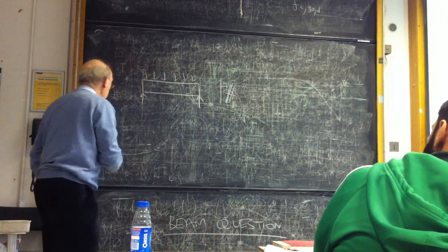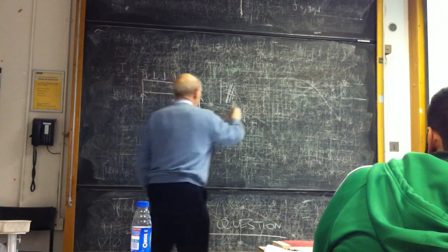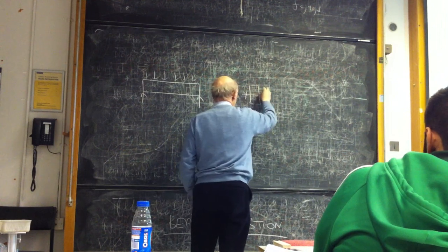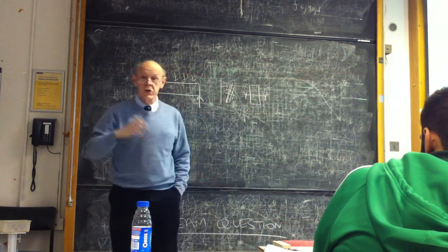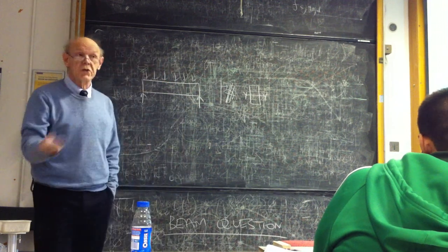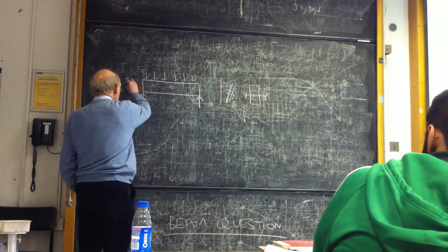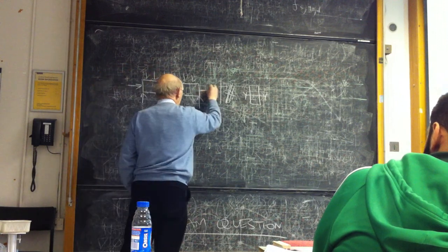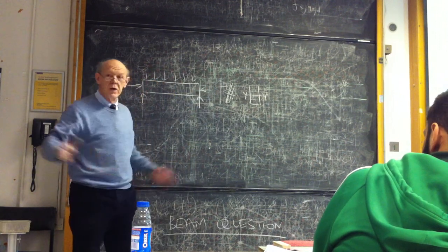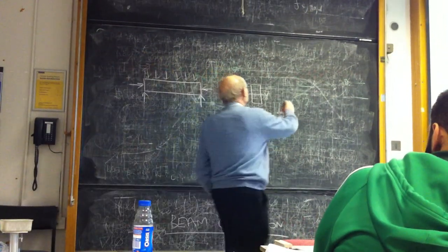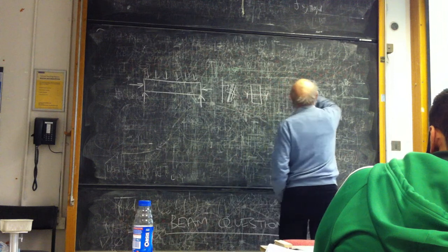Now this might get even worse. Now all we're really talking about is bending moments about one axis. It's a substantial bending moment because it's a beam, but it's only happening about one axis. But what happens if some kind person adds an extra problem to it by compressing the beam? Now that doesn't happen in beams, but where it does happen quite frequently is in a roof,